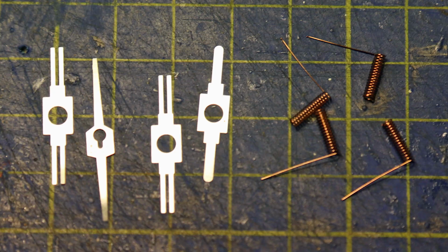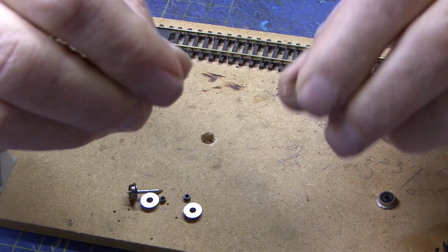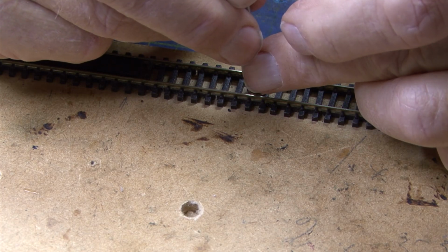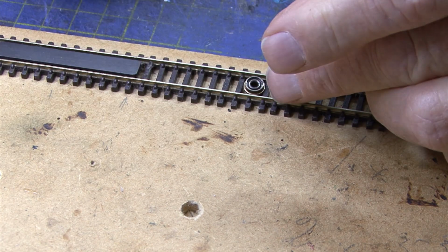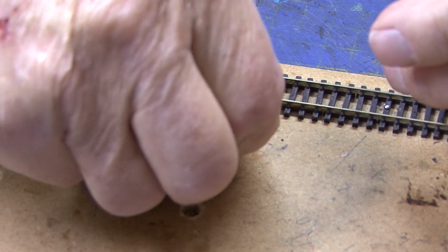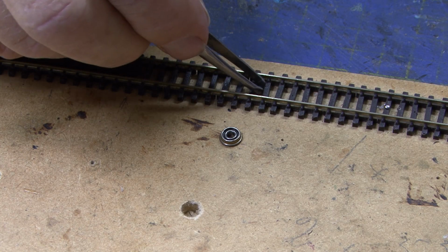We now come to the tricky bit: how to pick up the power from the track. Most articles on powered coach lighting focused on the pickups from the wheel axles with proprietary springs or pickup brushes. As all my axles are insulated, it is necessary to electrically connect one wheel to the axle. Two methods are suggested: drilling through the insulation ring and inserting a piece of wire, or removing the insulating ring and refitting it with a piece of fine wire which connects the wheel to the axle.